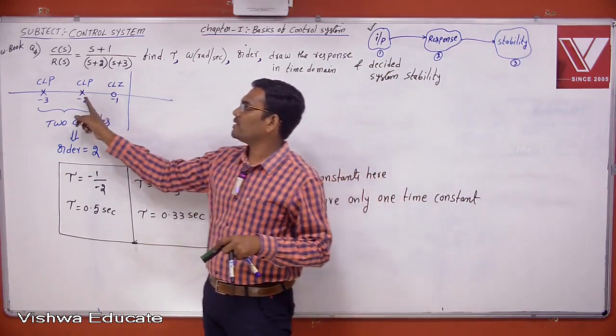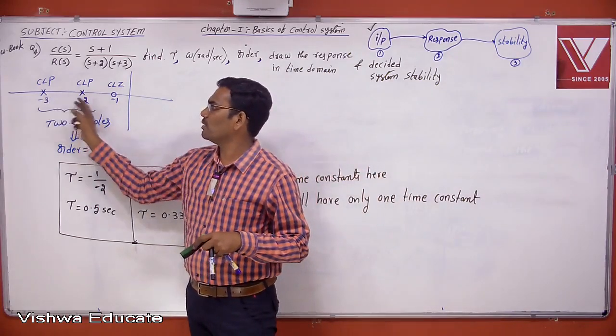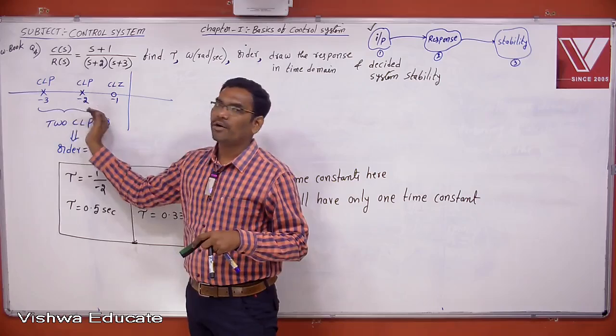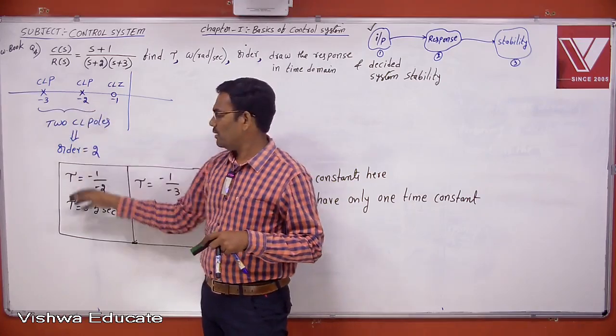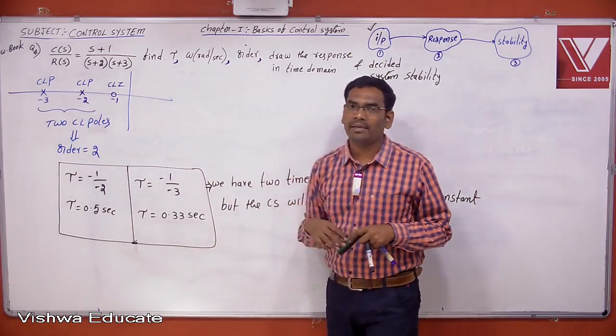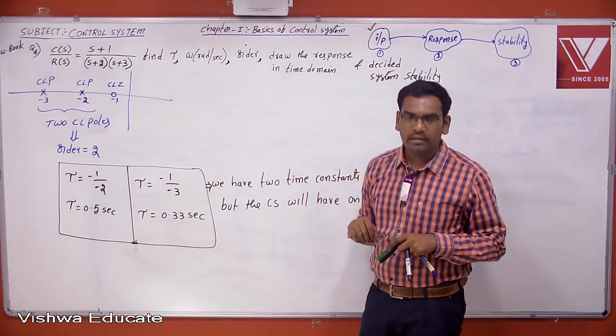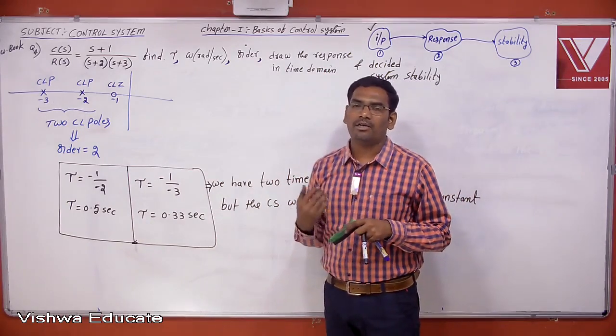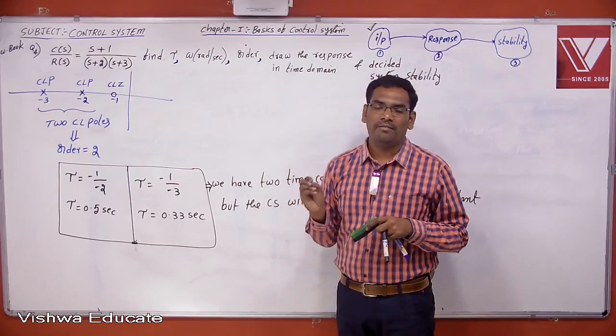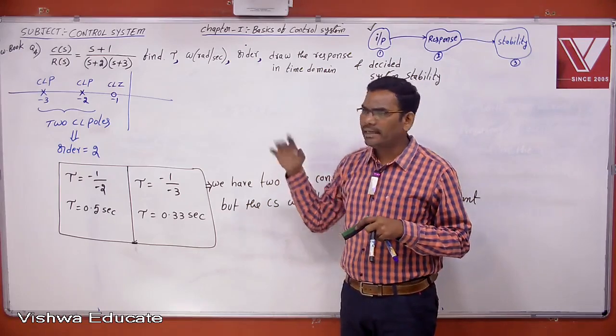But here the transfer function consists of more than one pole, so the formula we took previously is not matching here. Therefore, we want to find the standard formula for the system time constant for any number of poles.